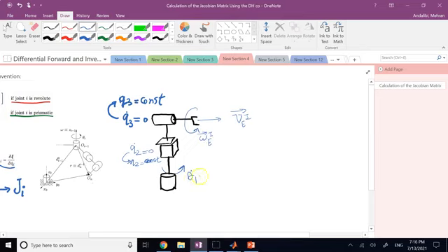So what's the effect of this theta 1 dot on each one of those if I lock every other joint? Well, first, what's the effect of theta 1 dot on omega? If I lock everything else, then the whole robot will rotate like a rigid body about the axis that this theta 1 dot is happening on, and it is going to be a pure rotation about the fixed axis. That's all it does, correct? It is a pure rotation about the fixed axis.